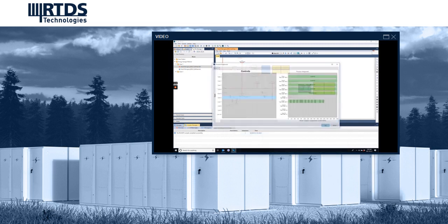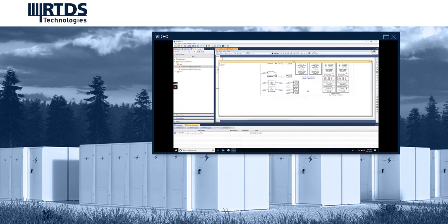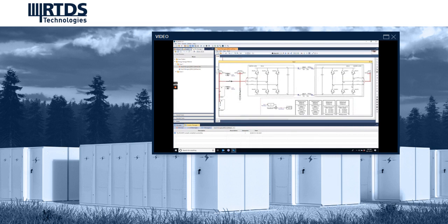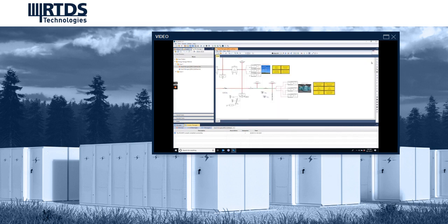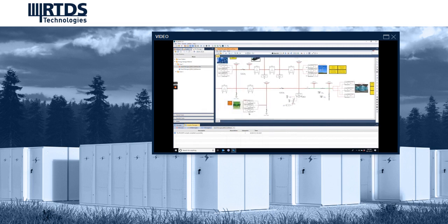The processor assignment requirements can be reduced by using switching function models to represent the operation of the converter without using the fully detailed switch converter models, which are heavily computation intensive. Next, we're going to see the real-time simulation of this battery system in the RTDS runtime so that we can get plots, meters and graphs in real time with the operation of this system.